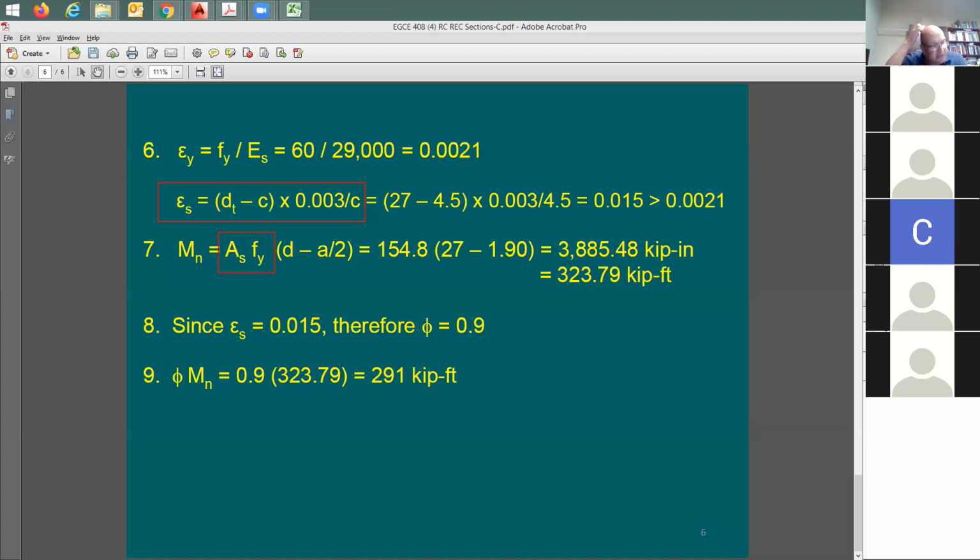Now, how about the grade of the steel? Just so you know, we have two common grades in the market. We have grade 60 and 75. 60 is the common one that you find everywhere. Don't try to go to 75 unless you have lots of rebars in your design and you feel the beam is going to be congested. It is going to be very tough to pour concrete. So in this case, you put grade 75, right? Does it make sense? So you know where to come up with the properties of the steel and concrete.